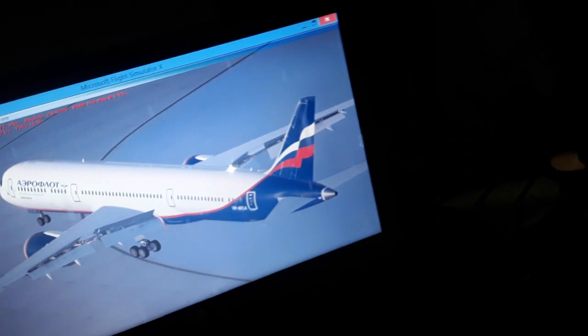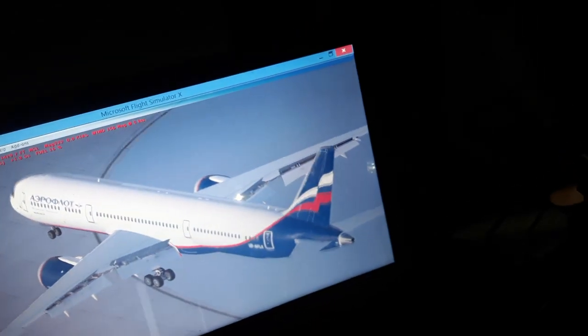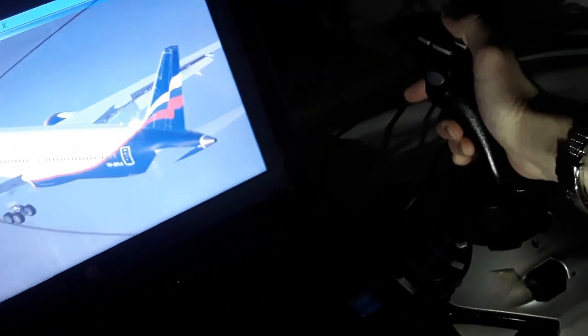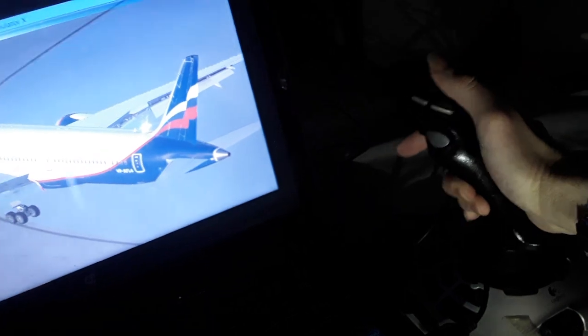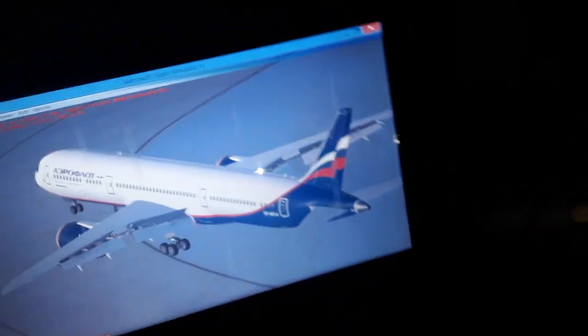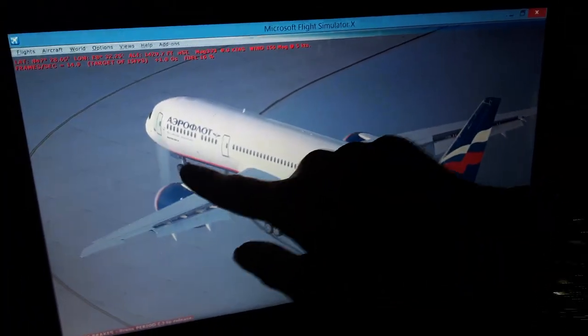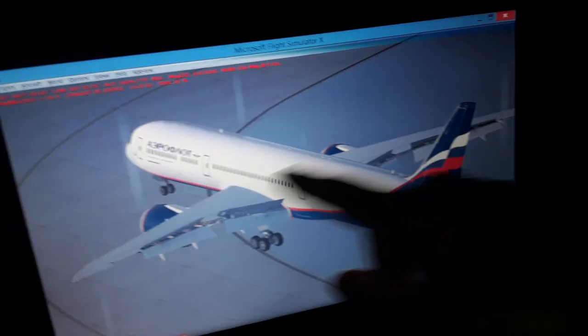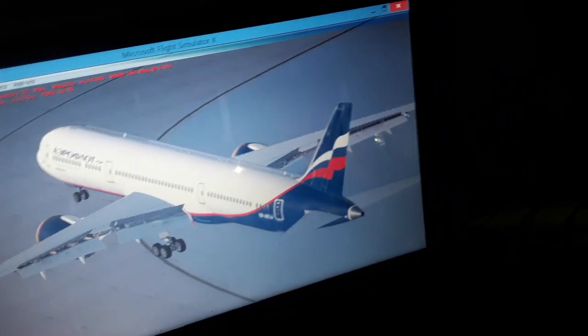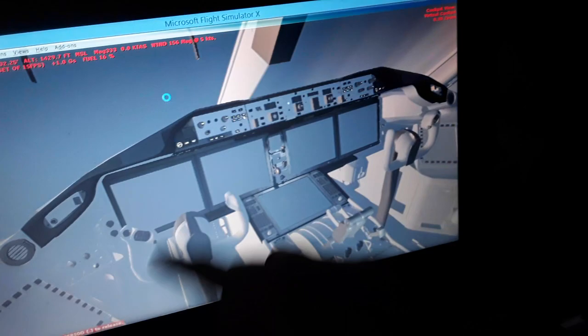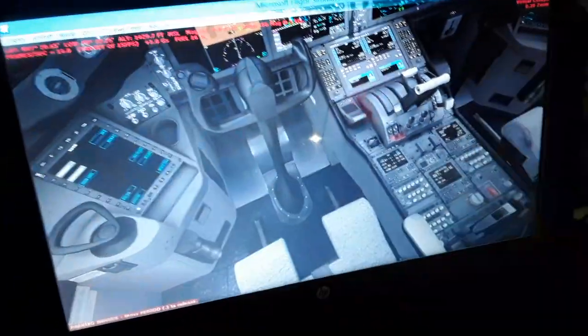Over here the elevator. So we have also the vertical axis, which is the yawing axis. We can use the rudder for making left and right turns like this, for turning the aircraft around its yawing axis. Or on the ground we can use the nose wheel steering over here, the nose wheels for making left and right turns. They deflect 76 degrees below 45 knots airspeed, as you can see, with the tiller over here.